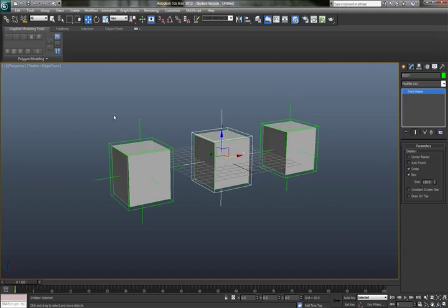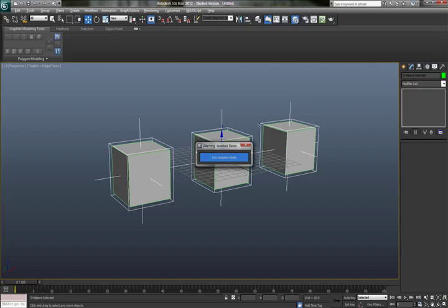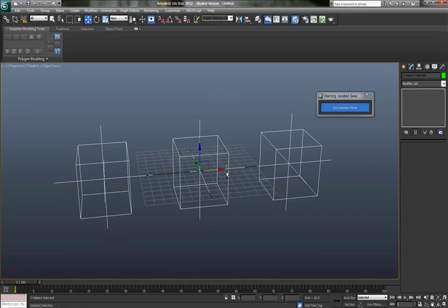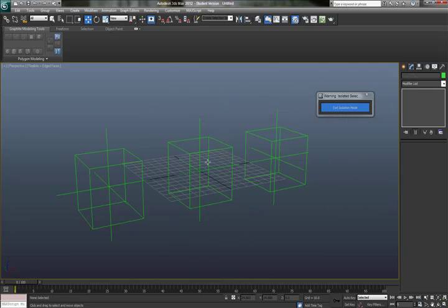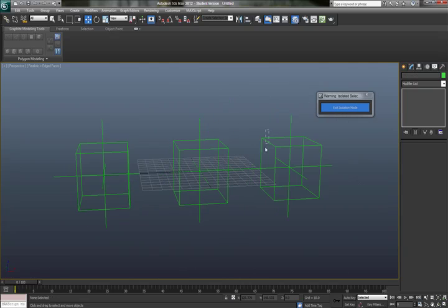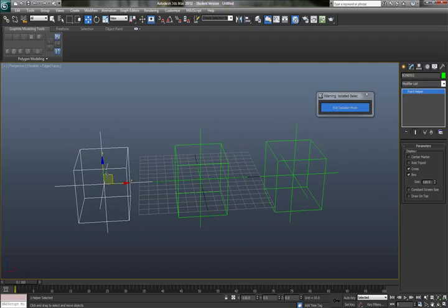So with that being the case, the next thing we need to do is I'm just going to go ahead and hold down Control, select just the bone objects, and hit Alt Q on my keyboard to isolate just them. So now these are not the meshes themselves, these are those individual point objects we created, and you'll see as I pick them here, bone 01, root, and bone 02. Now these are going to be the children of the parented object here.